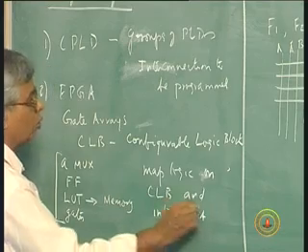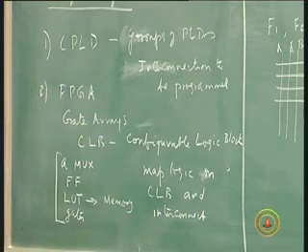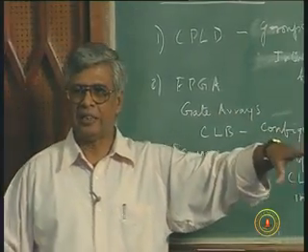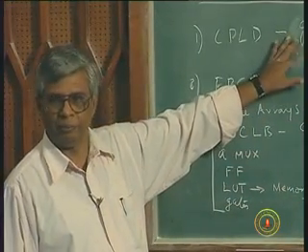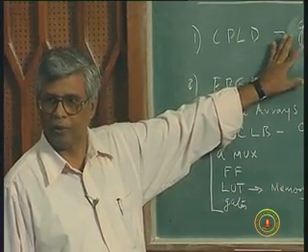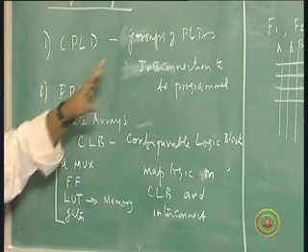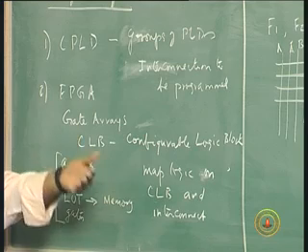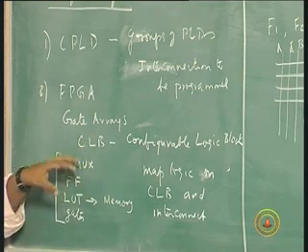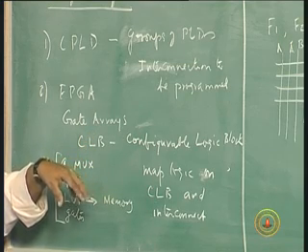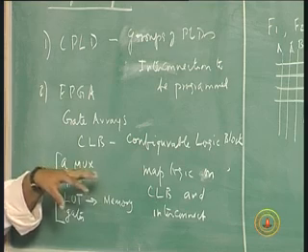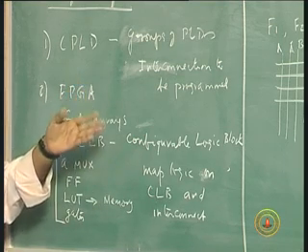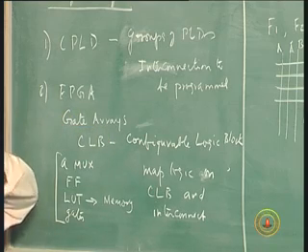That is the difference between these two. Here there are the standard PLDs which we are familiar with. They are available, there is a switch matrix, you program for switching and connecting them properly, you program only the interconnects. Here I have to map my logic, I have to break my logic into efficient blocks which can be fitted to each of these CLBs, and then not only map them efficiently, you have to interconnect them efficiently.